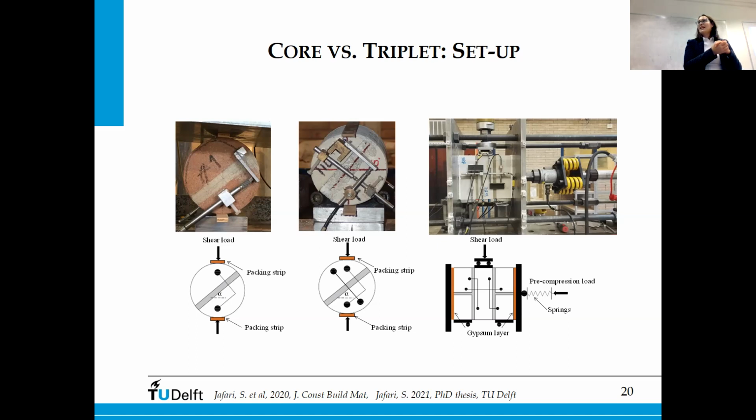But when you cannot touch the building at all, you can use cohesion and friction only and just obtain the crack distribution. I'm really trying to go for when you cannot do any kind of test at all. Actually, the homogenization can also work apart, to give the properties in a smeared way, without implementing it in full for structural analysis. That could still be one way to go. But of course, if you can implement it, that would be the implemented analysis. Thank you. I don't know if there are other questions.